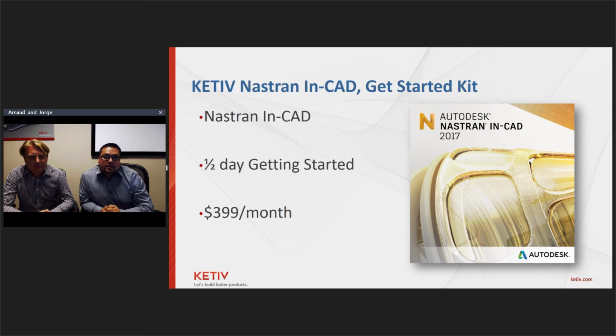Got it. All right, I'm seeing here from Tom, is the cut list exported to Excel? Does it update when adding items? So it doesn't update automatically. You would have to export it again. There are ways to get it to export automatically with the update, like on a trigger on a save using the iLogic tools inside of Inventor, actually. So if that is something you want to know more about, you can definitely reach out or talk to us afterwards, and that is something that is possible.